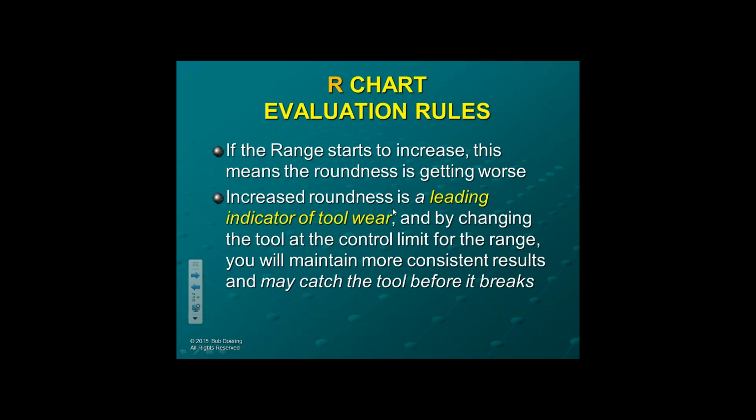You won't get that kind of information from an X-bar and R chart. So what happens is, let me go back. What happens is you have a continuum from cutting to rubbing as a tool wears. It starts off cutting, then it starts to rub. The more it rubs, the more it transfers the variation of the machine to the dimension, and you get more and more roundness.